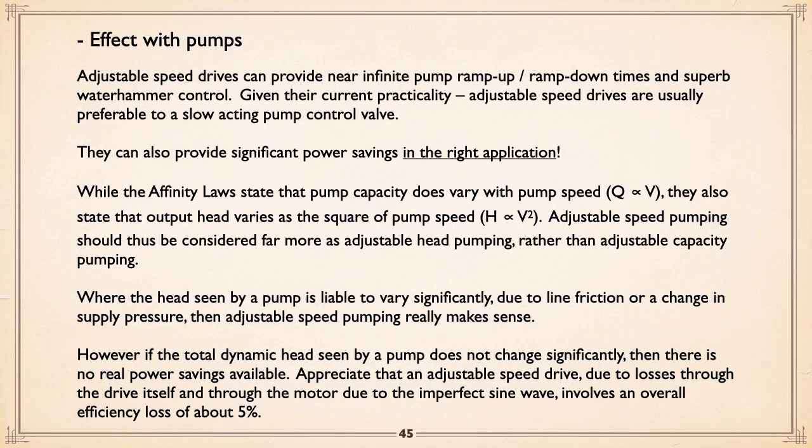Now, let's take a look. What does variable speed do with pumps? Variable speed, unlike a soft starter, which is 30-second limited because you're playing games only with the voltage, this plays games with the frequency and the voltage. Therefore, nearly infinite ramp up, ramp down times. You want to ramp it up over a day, go for it. Therefore, superb water hammer control.